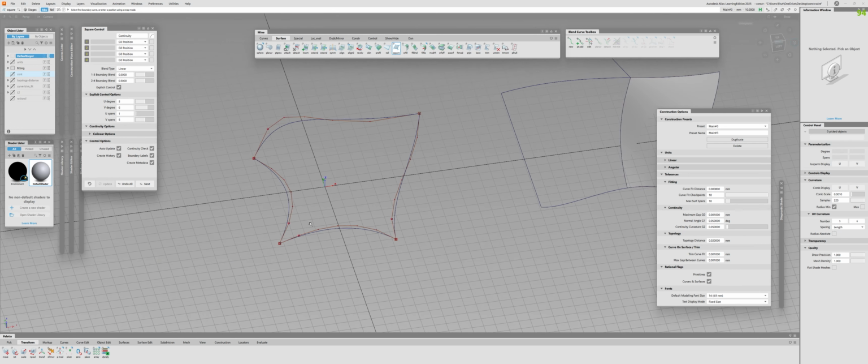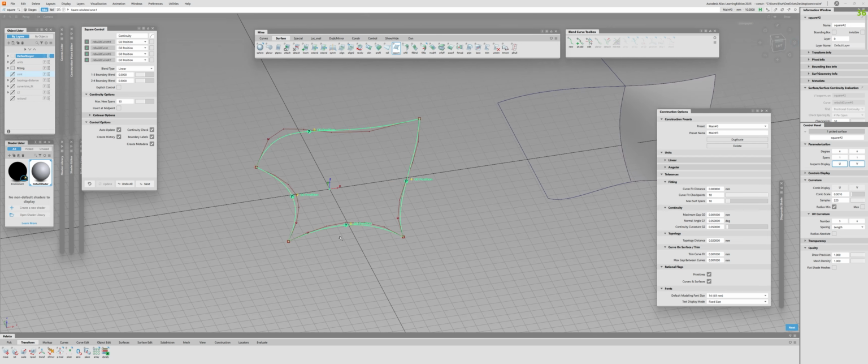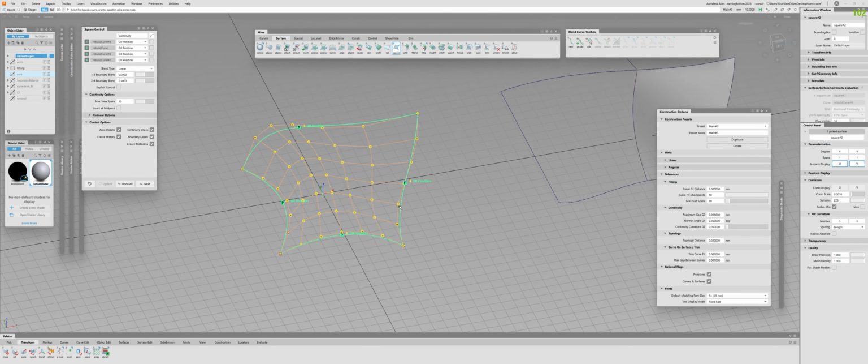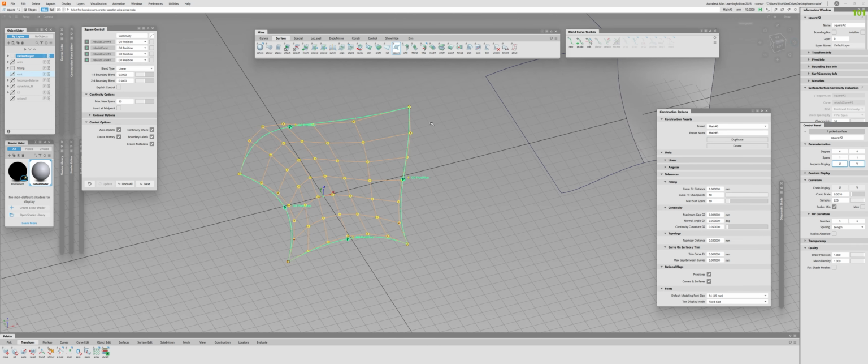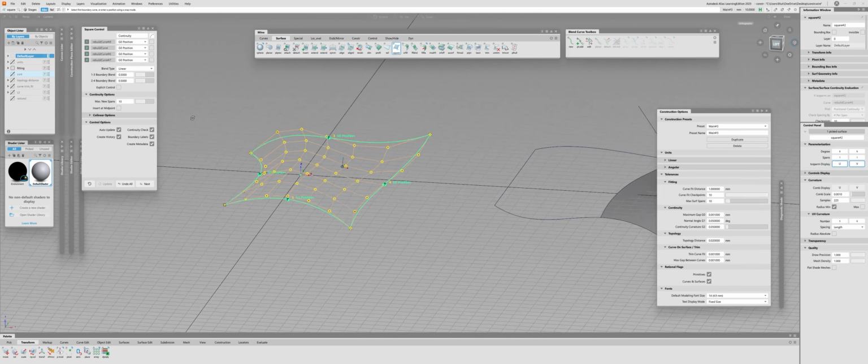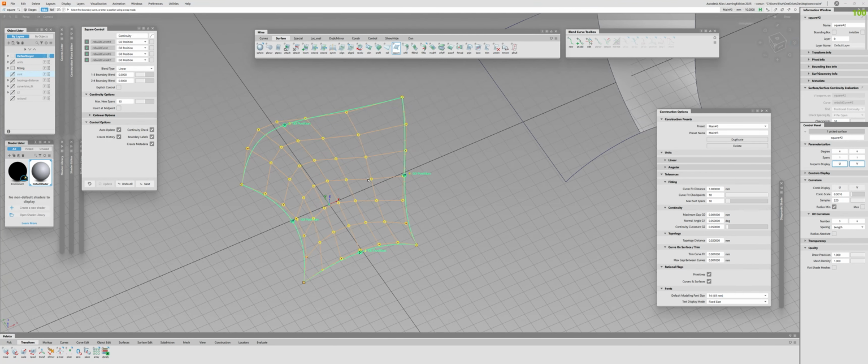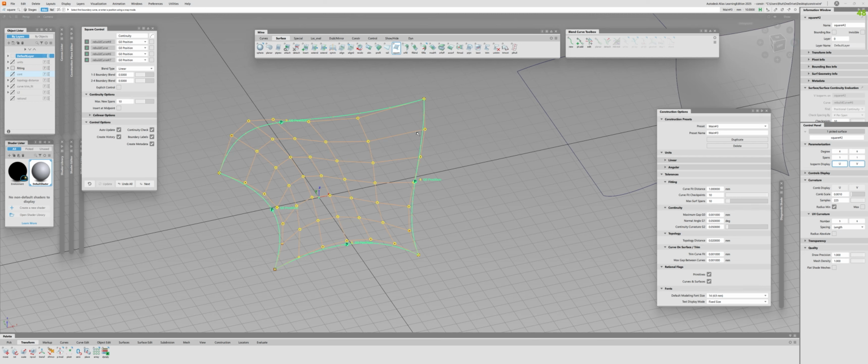Now, for example, I will create a square tool here, and let me just untick the explicit control. So let me just undo it and increase the curve fit distance to 1 millimeter. So it's very loose now. And I will create a square. Now, as you can see, Alias has little to no problem creating the surface around these curves, because these curves were very clean and accurate. 6 degrees, 6 degrees, 6 degrees, 6 degrees, they are all positional. So for the square tool, it's not a big problem to create the surface. And it actually created it to the perfect position.